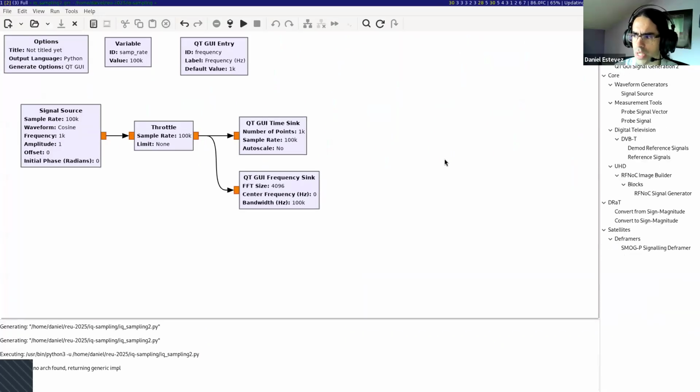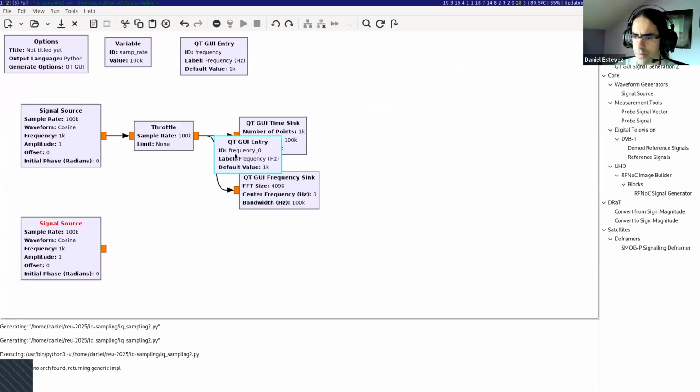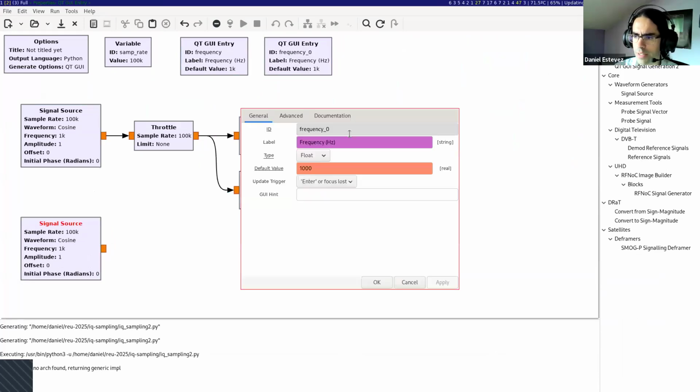So we are going to use the properties of trigonometric functions. I'm going to add a new cosine signal, copy and paste, and give it a different frequency. And for reasons that I will explain, I'm going to call this local oscillator frequency because traditionally, when this is used in a radio receiver or radio transmitter, it is called local oscillator.